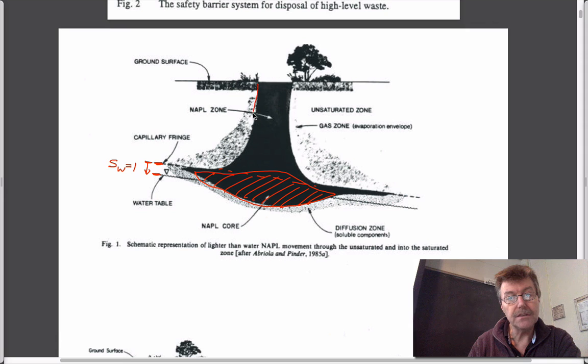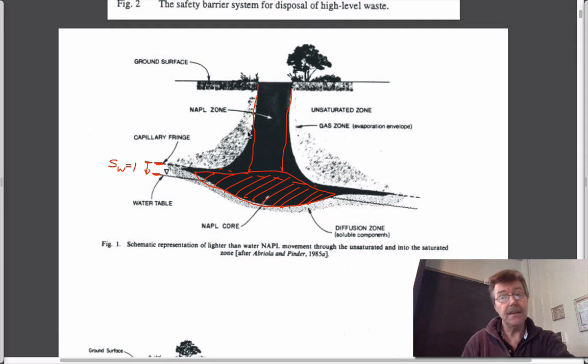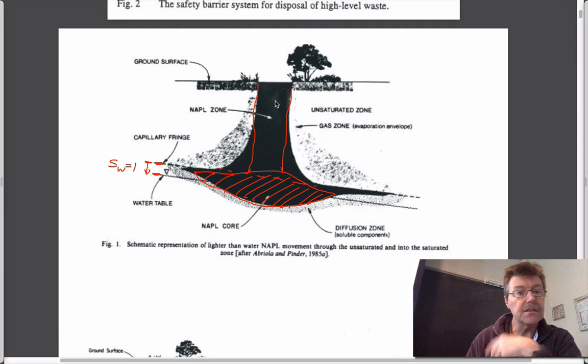We have this smeared zone as we come down here, which is this chimney in a simple way. You could imagine that if you drop some gasoline on the counter, you'd end up with a sheen of that material stuck to the counter. So this is the sheen that would be stuck around the individual grains in this column, in this so-called chimney. And then there's a zone where the 100% gasoline meets 100% water just below it, and is able to transfer mass across that interface by dissolution.